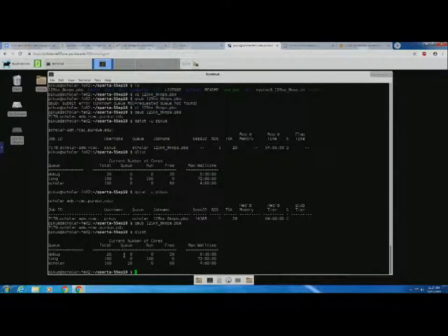It's usually 10 that is the bare minimum. So if you see that your cells are too small, where in some cells you have less than 10 particles per cell, then you know that there's something wrong with the refining process. In this case, I specified that my cutoff is 15. If I have less than 15, I coarsen. But it might be that it's not able to coarsen because you have one small cell squished between a bunch of bigger cells. Then you might want to raise that lower limit from 15 to 20, things like that. That's basically the best guideline based on number of particles per cell.